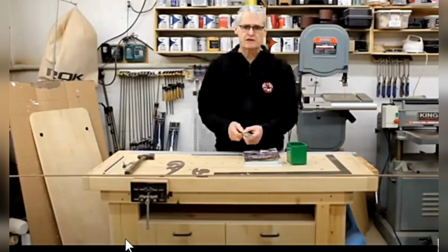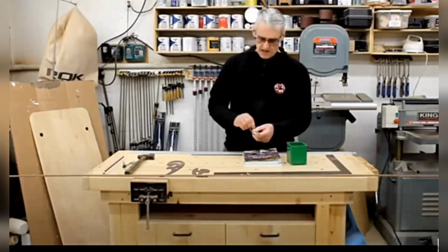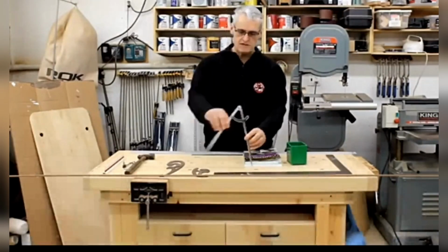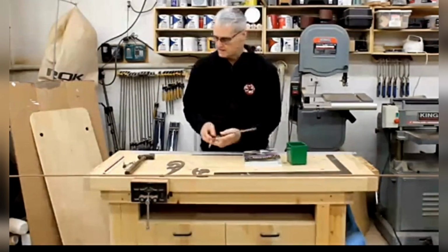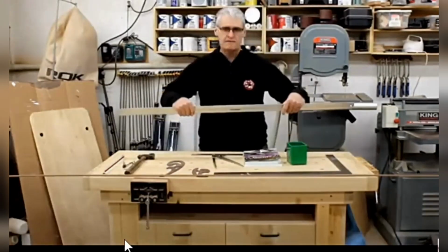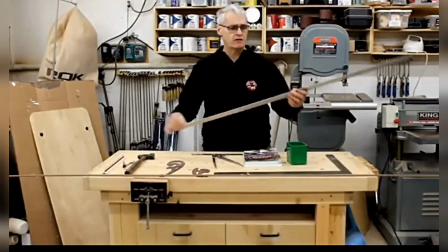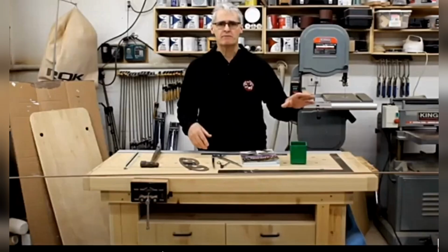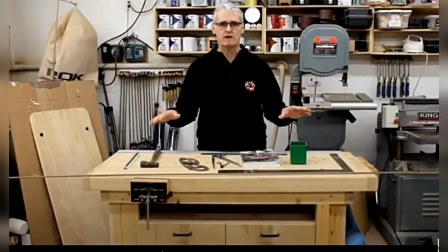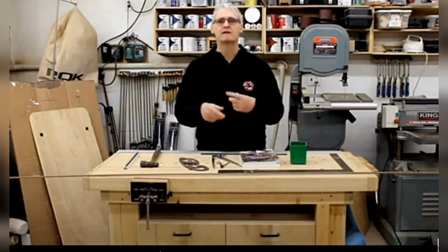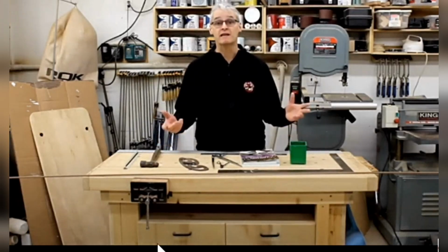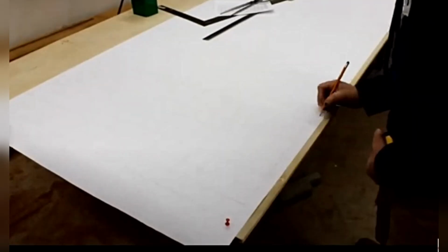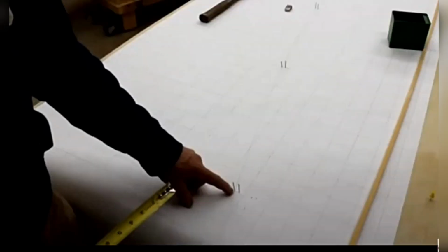what do you think you'll need for lofting? You're going to definitely need a nice good set of large calipers for marking some points or measuring and copying distances. Some rulers. I've got a nice 48-inch straight edge ruler. It's kind of nice and new. You've got some plywood, but I'm going to actually just put some paper onto the plywood so I can take my lofting plans, roll them up and move them away if I need to. This one here would be station number 1. That's what that mark is right there.